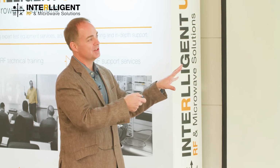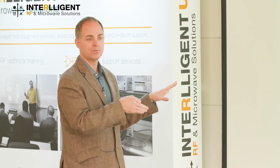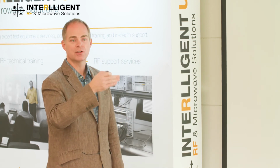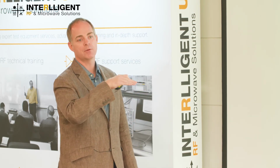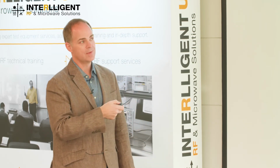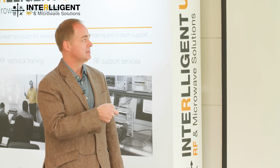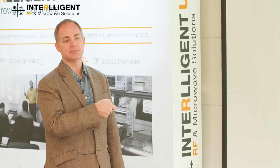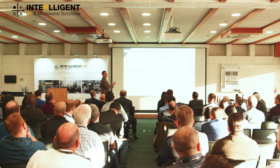For this particular technology, the failure mechanism is a little different than our lower frequency technologies. Typically, we see cracking in the gate structure or the field plate structure in the lower frequencies. This is actually a different failure mechanism that has to do with metal mixing that occurs. The gate itself is actually much more robust, so we don't actually see catastrophic failure. When we fail these, what we typically see is a degradation in performance that's not recoverable. So we actually spec this as a degradation as opposed to an actual catastrophic failure. So this is an extremely robust process.